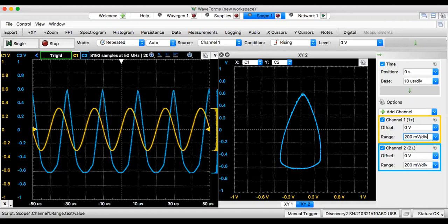Actually, here we are not worried about crossover. We haven't reached the crossover point yet, but we still have distortion. So that's called harmonic distortion. Not only do we have crossover distortion, we also have harmonic. So we have 2 distortions: a crossover distortion and a harmonic distortion.